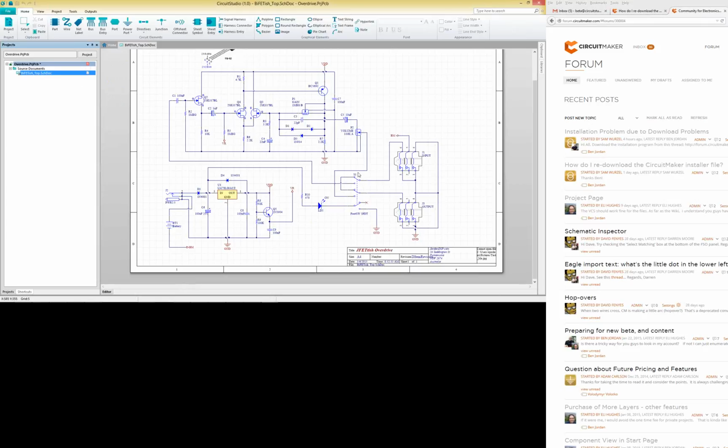A couple of things to note. This was done in Altium Designer. But you'll see, because I added an existing schematic, it has not actually made a copy of the schematic. What it's done is it's just linked it to the project. And I can see that by this little icon overlay. I don't know if you guys can see that easily over the web, but it looks like the link overlay that you get on the desktop with links.